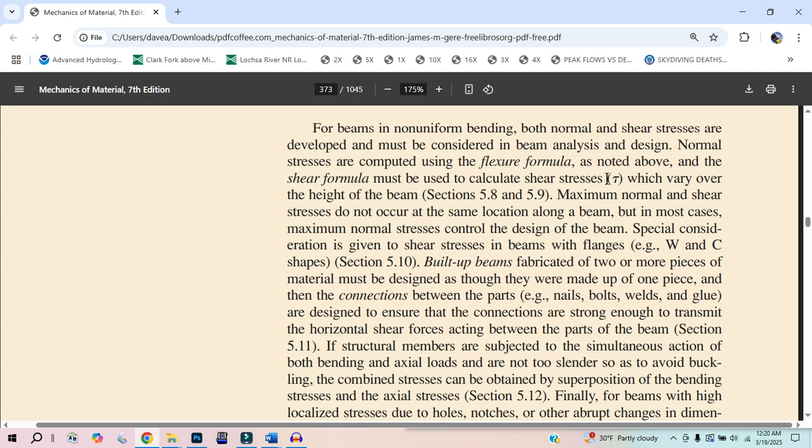If you see a change in length of this beam, and you know your neutral axis is right in the middle, and you have a certain shape, you can take some of these problems and turn them into straight geometry problems. I know the neutral axis is going to be in the center of something that's bending. I know its shape is going to be just due to the moment, even if there are shear forces involved, because we just talked about that.